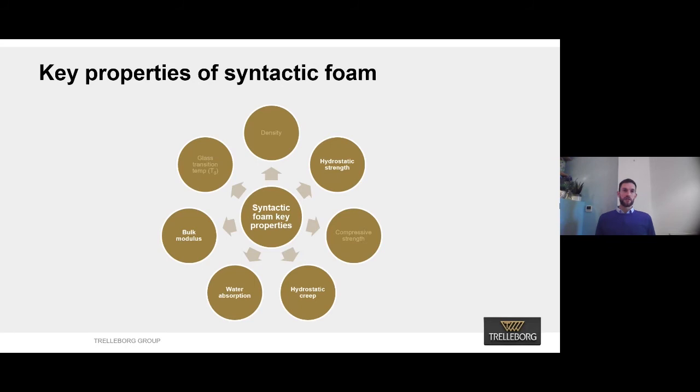Those properties are hydrostatic strength, so what pressure can the material resist without collapsing or crushing? Bulk modulus, so how stiff is the material? How much will it compress at a pressure subsea? Water absorption, how much water will ingress into the foam over the design life? And hydrostatic creep. All polymers typically creep under load, so how much is this syntactic foam going to creep over the design life?